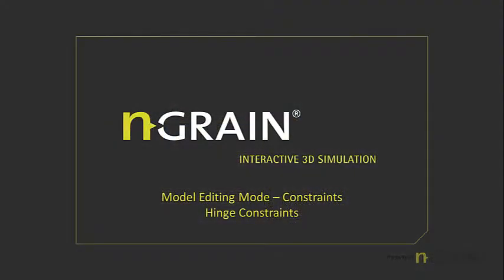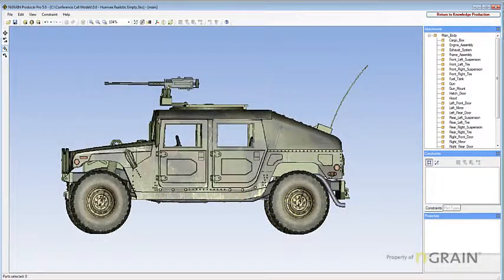In my first example, we'll be using a hinge constraint. You can create a hinge constraint that allows you to restrict the rotation of a part, such as a dial, switch, or door. This allows you to create animations that accurately depict how a part works in the real world and task steps that require learners to move a part in a constrained manner.